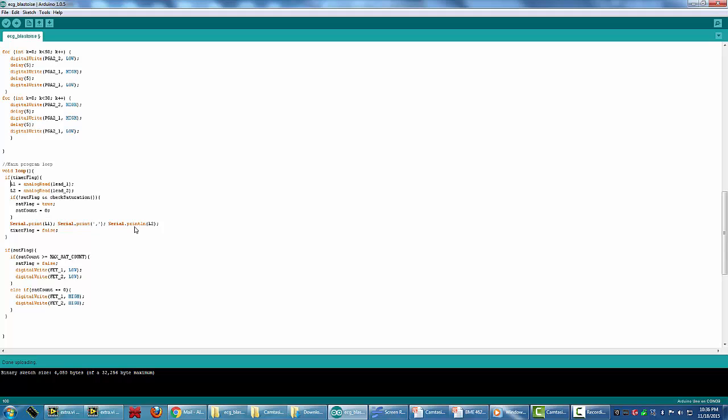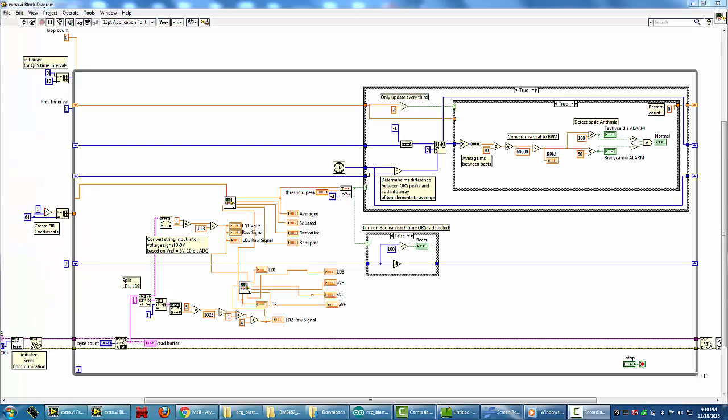So next we'll look at our LabVIEW code. So here is our VI for our ECG that takes in data and does some processing. This VI consists of 2 sub-VIs, one here which does simple lead calculations by taking in lead 1 and lead 2 as inputs and calculates lead 3 and some other variables.